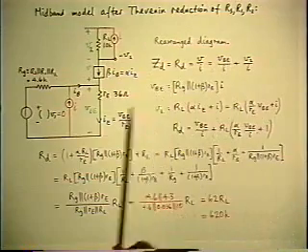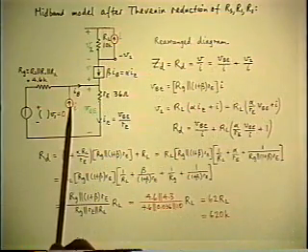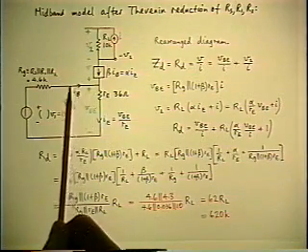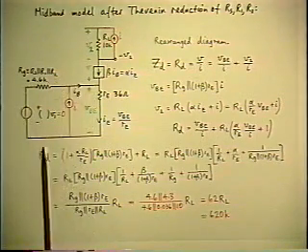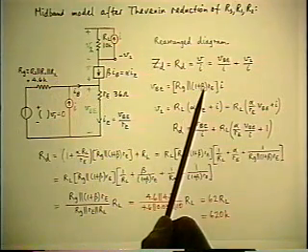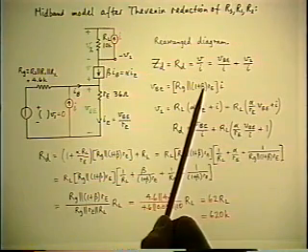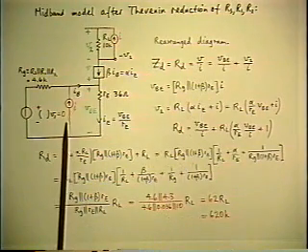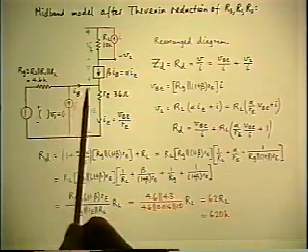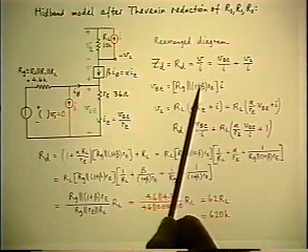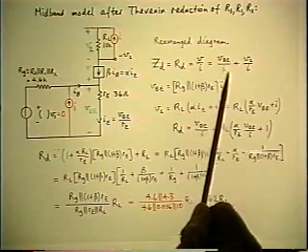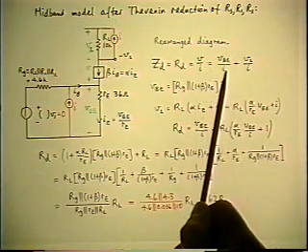I can find the VBE as a function of I because I have a current source I developing a voltage right across it determined by the resistance RG in parallel with the reflected RE. This is just a Norton source here, basically. The impedance across the source is RG in parallel with the reflected RE. So this is the relation between VBE and I. That takes care of the first term in the result I'm looking for.